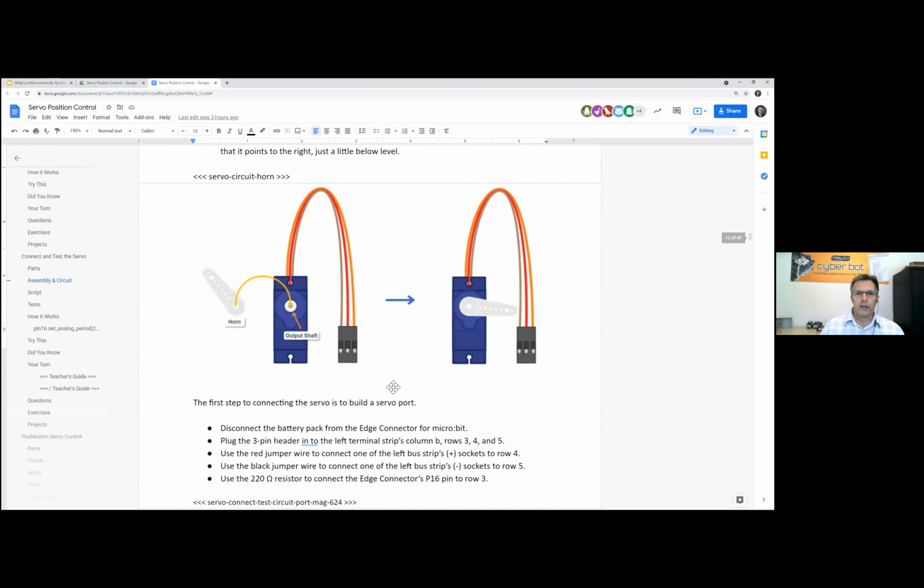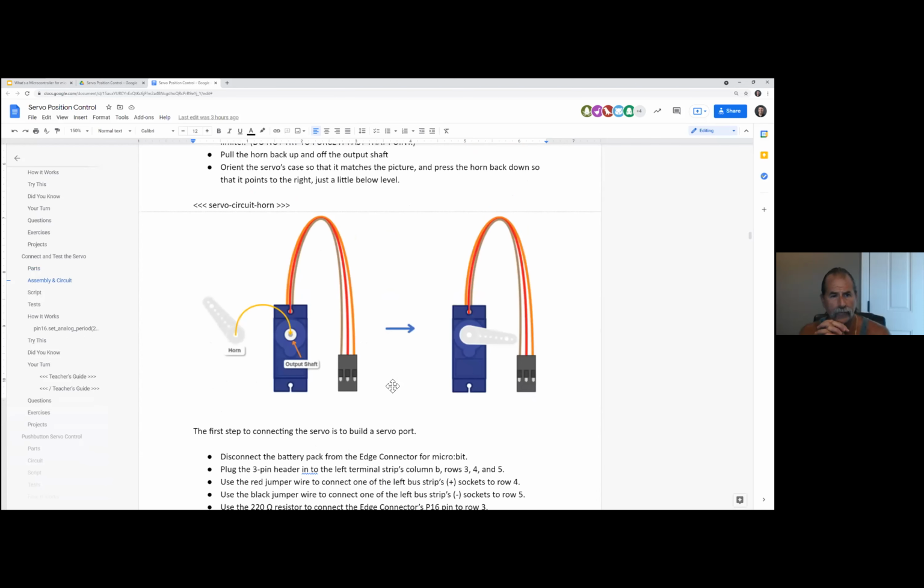You know why, Andy, that of all the standards, servos use brown versus black, when brown and orange can frequently seem so similar? Every other device or sensor, except for servos, follows that normal standard. Yeah, I don't know why. The Parallax servos all do black, red, white: black for ground, red for power, and white for signal.